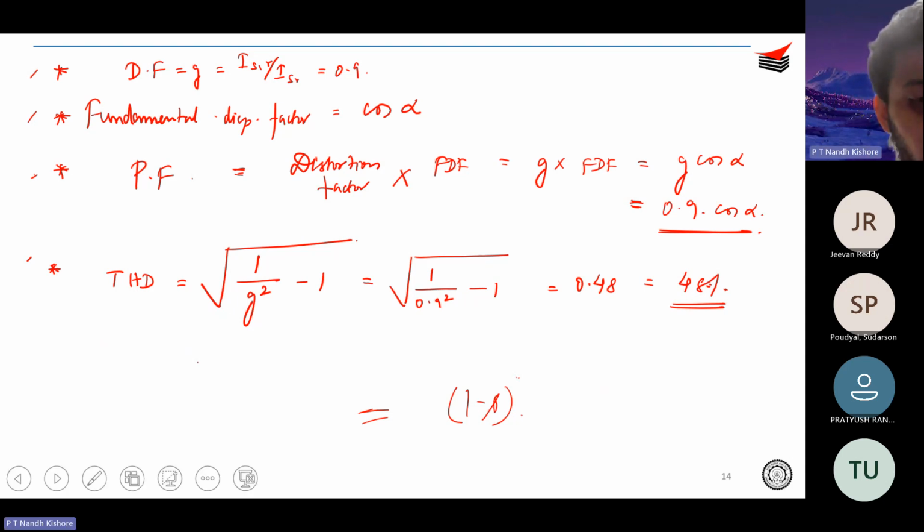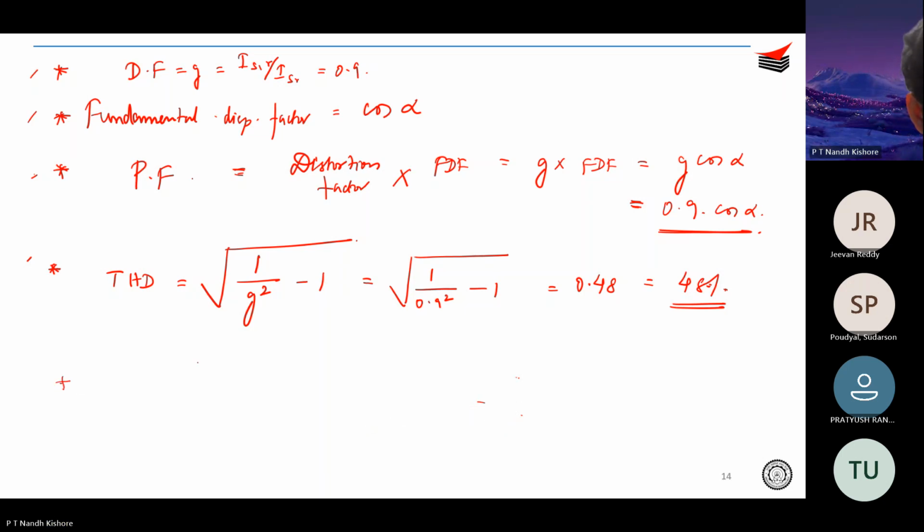So there is one more thing over here. Now you understand that you have a THD, you have a power factor. When you say that you have a power factor, obviously there is some reactive power and active power flowing. Active power is what you wanted, but unfortunately you also got a reactive power because the power factor is not unity and your current was not sinusoidal.